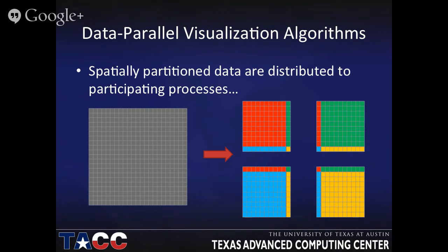Does that make sense to people? So that means, for example, if I have a curved surface that goes from here through here, and I'm computing the surface normal by looking at the gradient in this region, I have all the data in the vicinity to compute that gradient from. If I didn't do that, I'd have only these 2 cells to compute the gradient at this point, and only these 2 cells to compute the gradient at that point, but that point is actually the same as this point. And so I get a different answer for the 2 partitions. And you will see a seam in smooth surfaces that derive from exactly this problem.